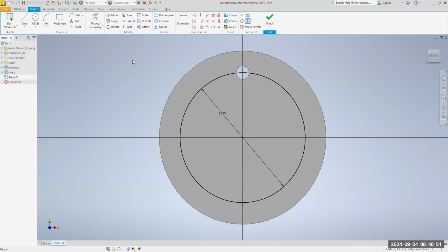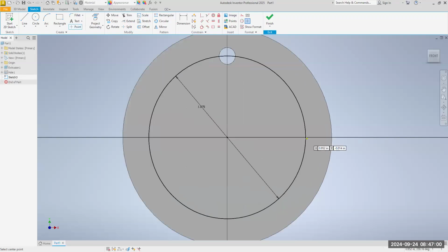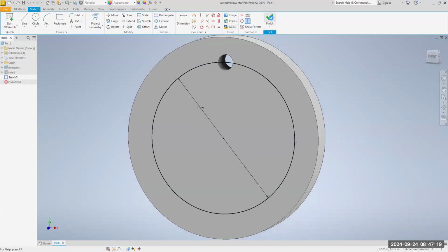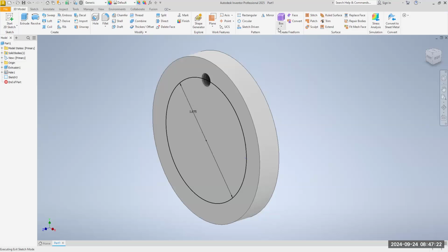All right. We're going to put a point here. Select point and go to the 3 o'clock position, and you can feel it. You can actually feel it in the mouse. So select this point right here. Do a right click, select OK. You can't see it, but if you hover, you can see it. If you hover over that point, you can see it. Finish the sketch. Notice how each hole has its own sketch. Okay. Select hole.